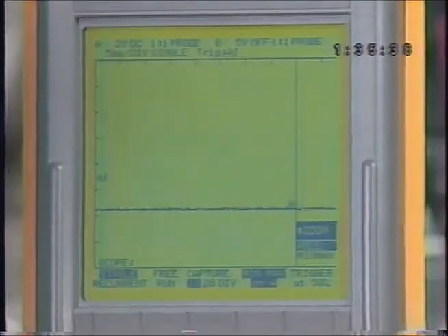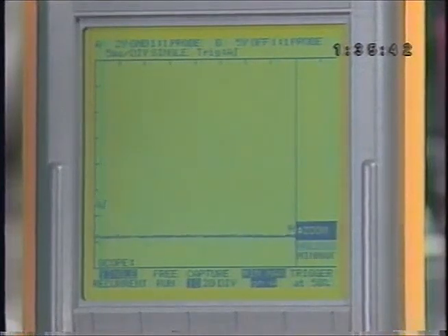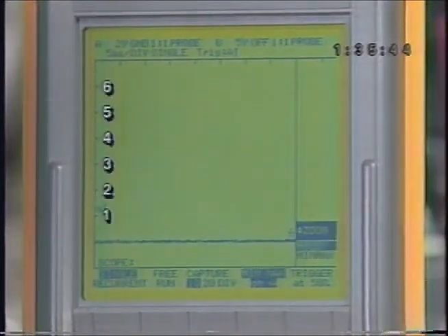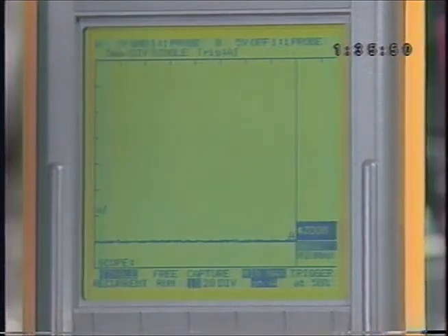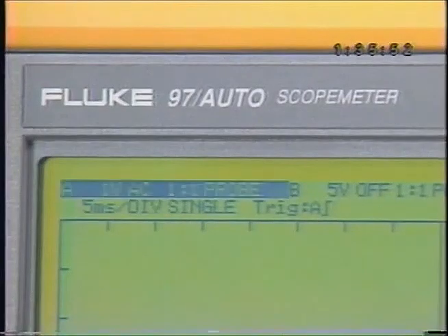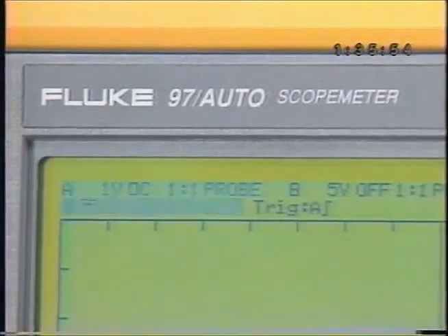Adjust the ground level to the bottom voltage division and use the voltage readings you took to choose a value for the voltage scale. Since the maximum voltage was 4.46 volts, 1 volt per division is a good choice for the voltage scale. Choose DC coupling and set the time base to about 500 milliseconds per division.